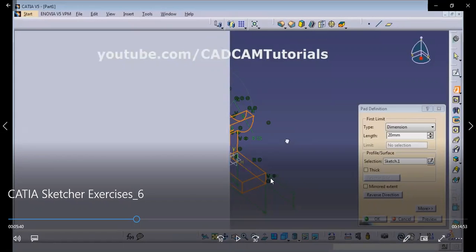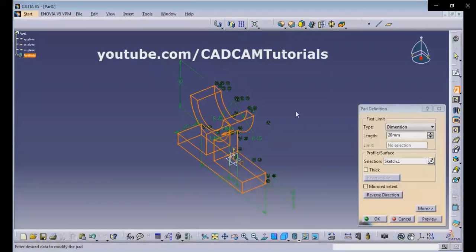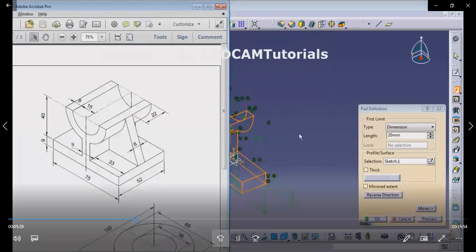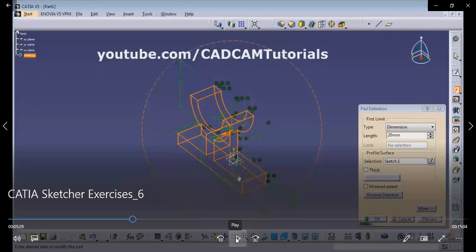When you want to do it on both sides, you use that, so that you can specify half the distance and it will take the pad on both sides. I want it on both sides so that I will get this center plane to create this stiffener.